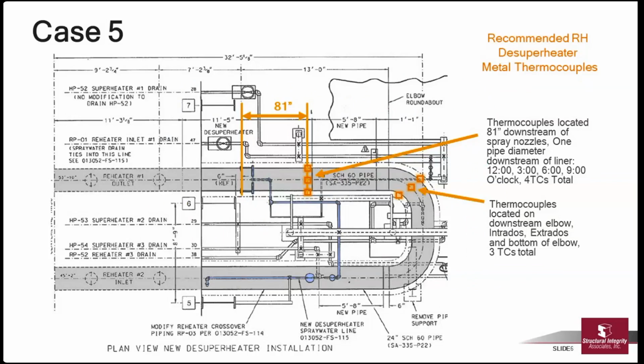So if you have sprays too close to the upstream elbow, that non-uniform steam coming into the sprays, even if the sprays are uniform, which is in itself questionable, is going to push that spray up to one side or the other. So adequate upstream and downstream length are important. I think finally people are starting to do that in their designs, but historically that was not the case.